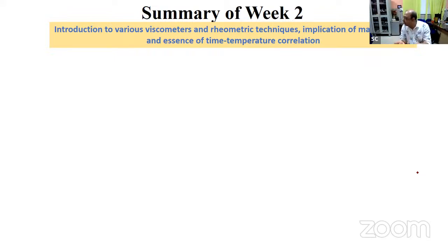So you call it dynamic rheological measurement. The same thing done at a lower temperature you call dynamic mechanical properties. So it really doesn't make much of a difference in terms of conception. DMA or rheology is an inherent property of the material; nothing is very unique, nor widely separated from dynamic mechanical measurements. Conception-wise, you just have to see the temperature involved and the equivalent frequency, which in rheology you call shear rate. That is what you do in terms of interpolation and extrapolation.